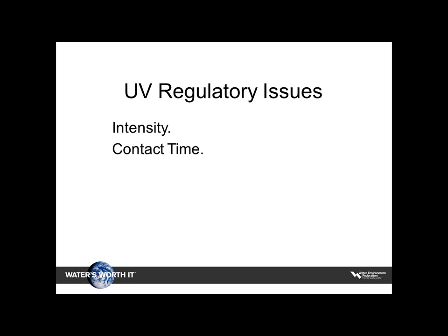How long is my contact time in there? What hydraulics do I have to deal with? Again, I need to keep the lamps always fully submerged. What type of redundancy do I have to have on this? Do I have full redundancy in that?